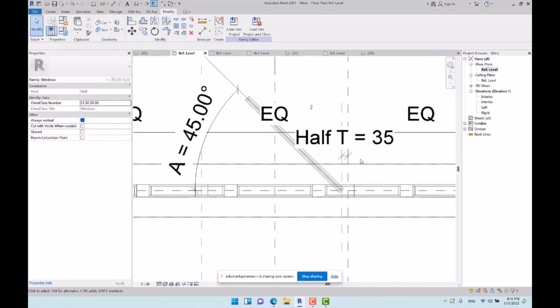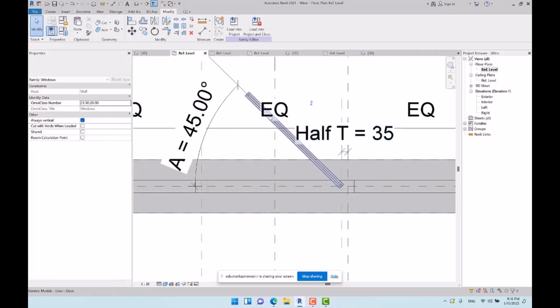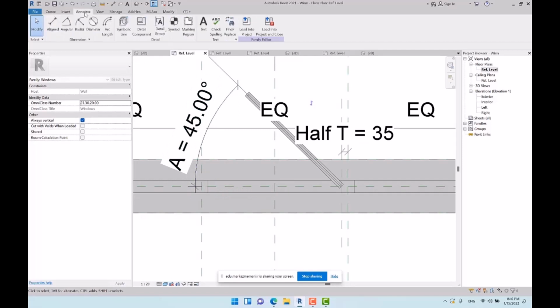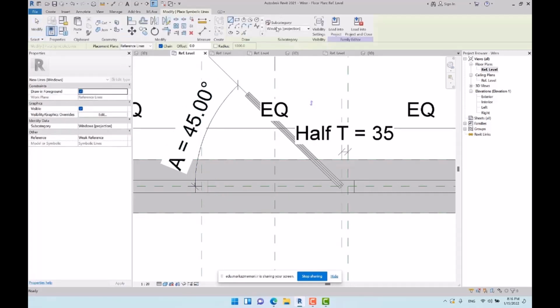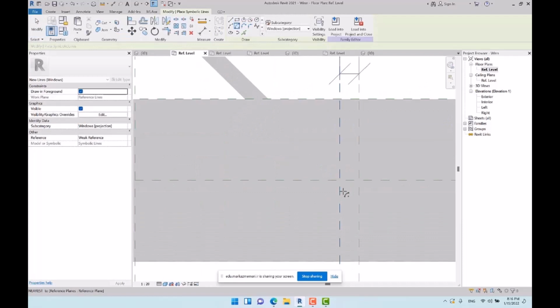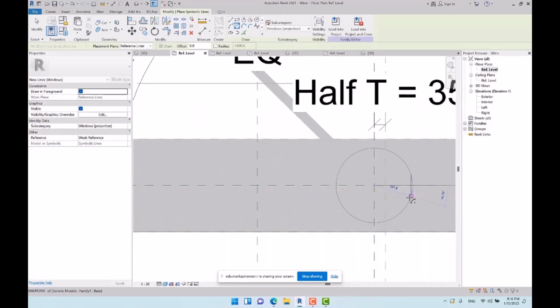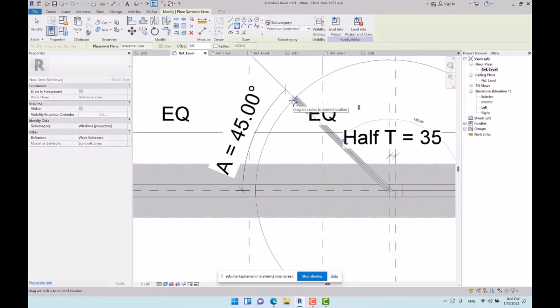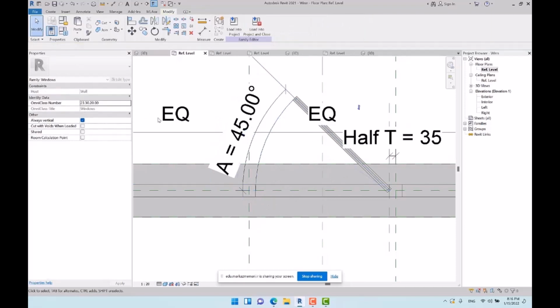The next thing that we should work on is to define the path of the opening actually, that could be an informative lesson for displaying the route of the movement of the door. I want to use symbolic line. I specify a point from here and then the desired location, middle of the door, and then I extend these to specify the endpoint, and then I lock it.